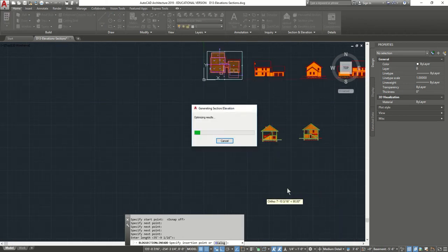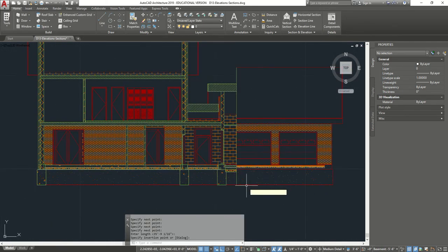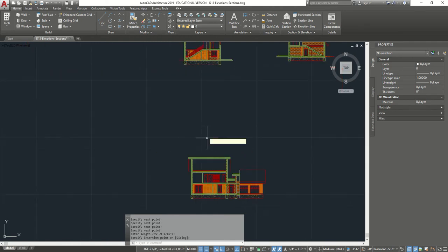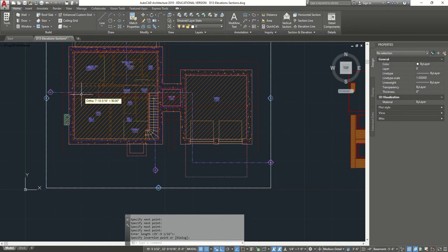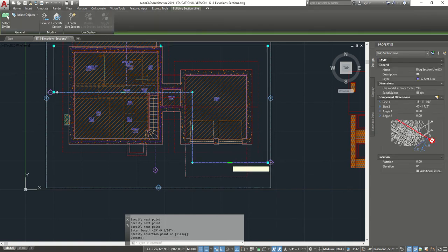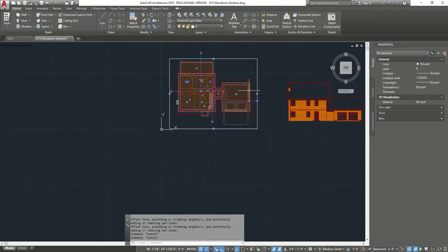You're going to notice that the garage door is going to be a solid and the other one not. Why? Depending on how I cut through it. If we look at the reference line, I'm cutting through the building here. I'm stopping, going outside the building, so now I see the exterior, and then going inside. If I don't want to see that, I could grab here and pull it inside the garage. I should make a straight line at this point.